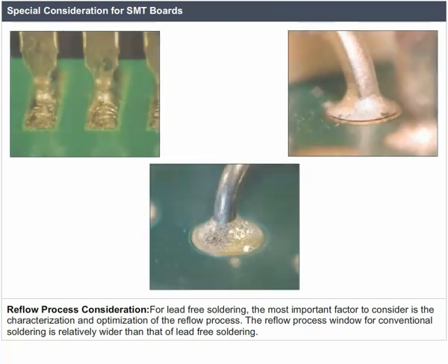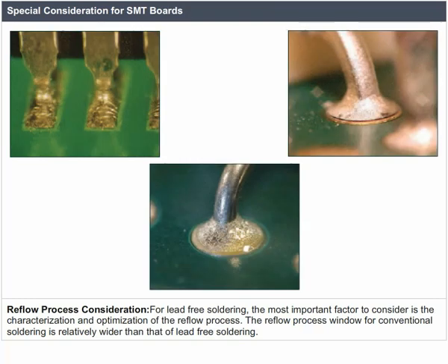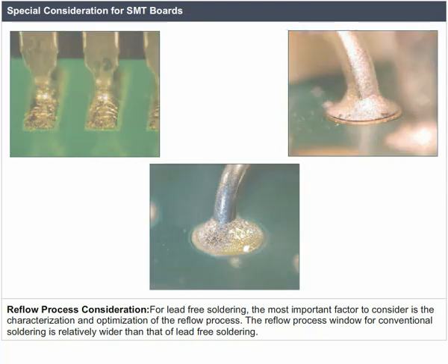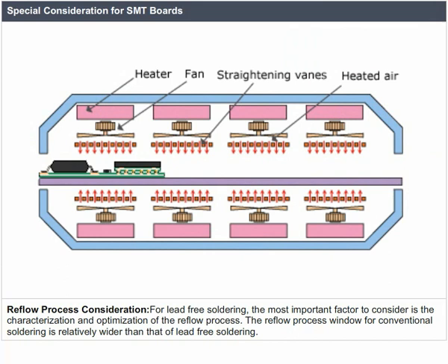Reflow process consideration. For lead-free soldering, the most important factor to consider is the characterization and optimization of the reflow process. The reflow process window for conventional soldering is relatively wider than that of lead-free soldering.